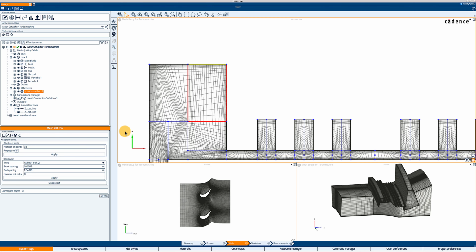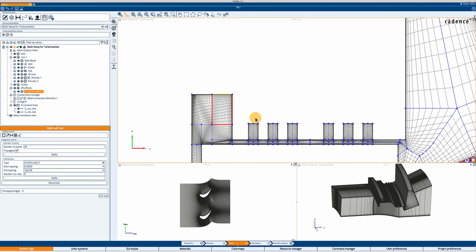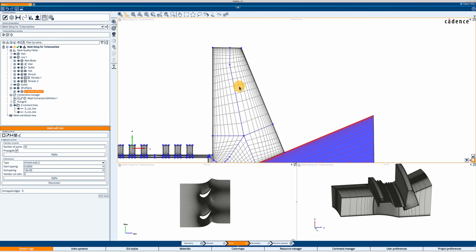You can also delete and recreate blocks. So let's take a slightly different block. I'm going to click on this one. I'm going to click again on the same segment because I want to select the other block. So right there, now it's highlighted in red. That's the block that I wanted. By just clicking on the segment multiple times, it will go through the different blocks that contain the segment I'm clicking on. And I'm going to delete this block.